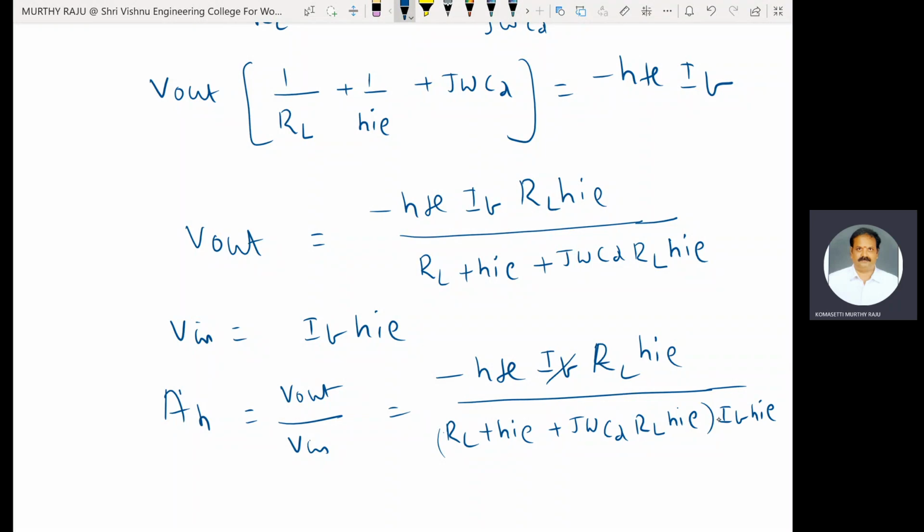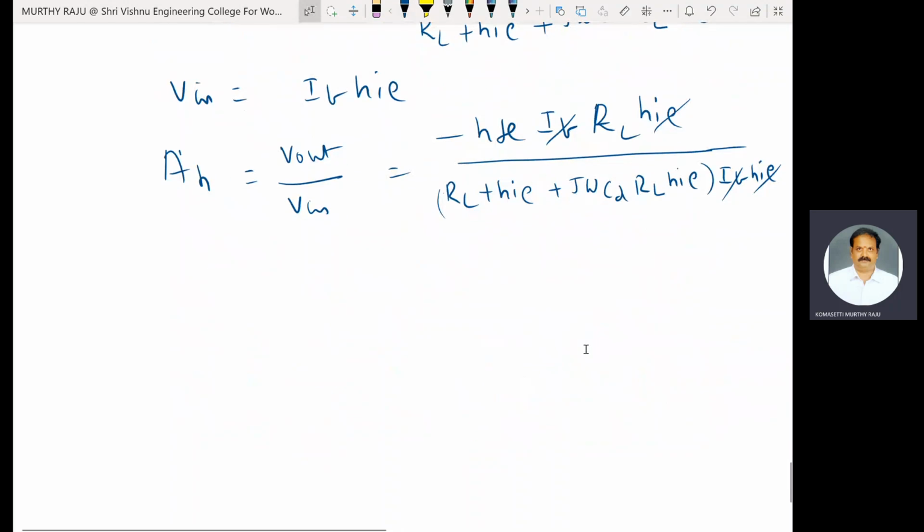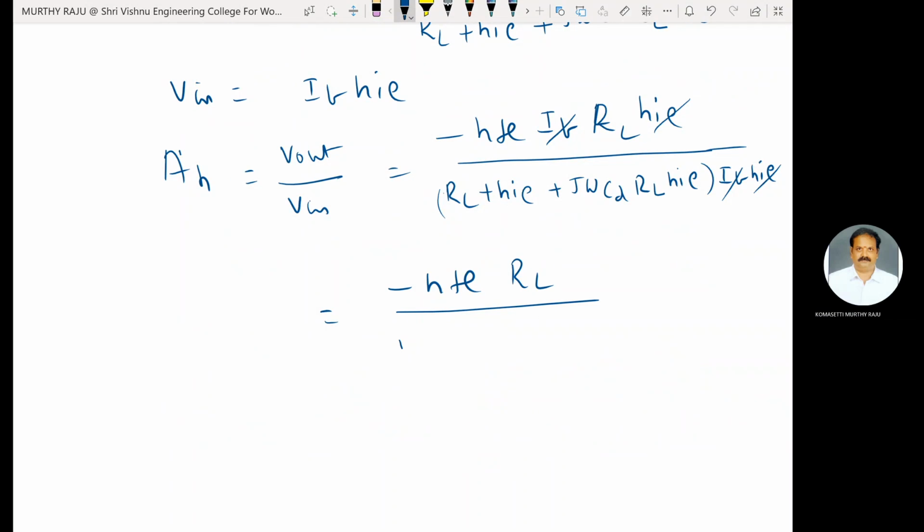This IB is cancelled, HIE is cancelled. Therefore, finally, AH is equal to minus HFE RL by RL plus HIE plus J omega CD into RL HIE.